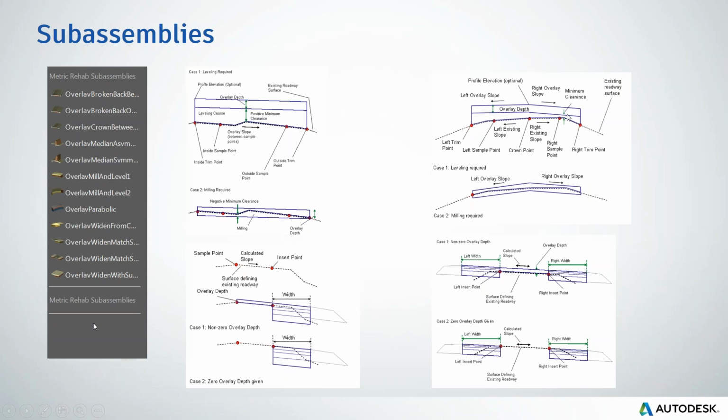You can define a minimum clearance because you want to add some material here, and you want to achieve some minimum clearance because you know that this road is not very good and you need to add something, at least, for example, a couple or 5 centimeters of new material. So you have all this information, or better said, possibilities available.